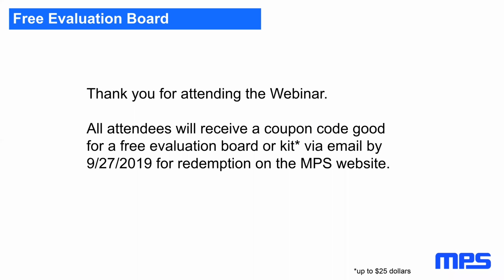Okay, thank you, Christian. So the next question is, how do you calculate the decap value depending on EMI noise? Yeah, most times you have more capacity than you need. So the EMI noise at the higher end typically is more dependent on the parasitic inductance of your ceramic capacitors, the magnetic field the capacitor puts out, the electric field your inductor puts out.